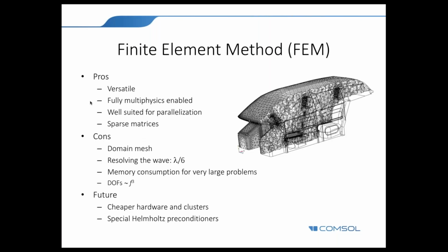So this is the finite element method and the finite element mesh. We will use this for our model, and we will open it up soon to see what the solution looks like. It has its own pros and cons. It's very versatile. You can use it with any other physics, so the full multiphysics capabilities can be used, and it's easy to parallelize. But on the other side, it can be a large model. You need to resolve the wavelength well to get proper and nice results. And of course, for larger models, the memory consumption can be huge.